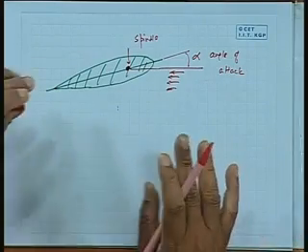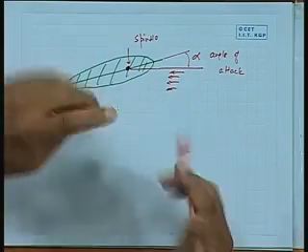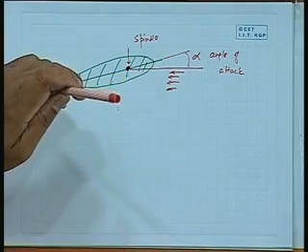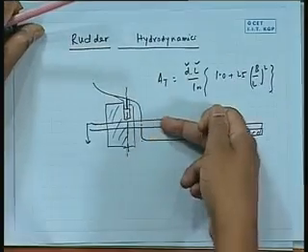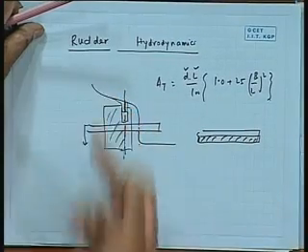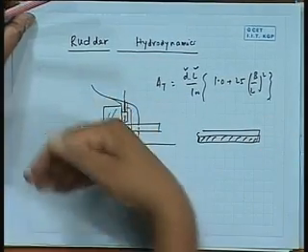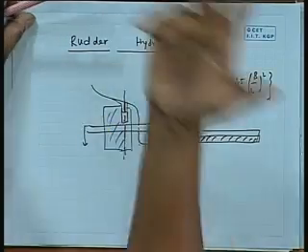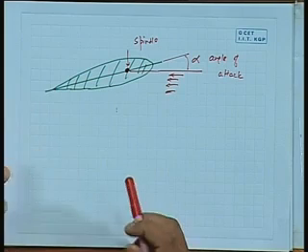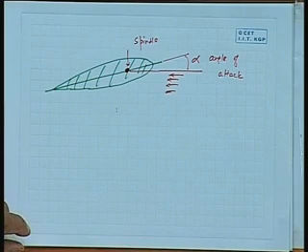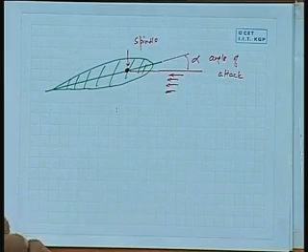Let me again say, if you take a cross section of the rudder, see, first of all, why cross section for hydrodynamics? It is only obvious because you would expect the flow along the rudder to be along this line, not having a vertical motion much. So any cross section you take, you can find out, and you can take each cross section, add them up, you will get the total force more or less. So therefore cross section is a very logical approximation, and I want to tell you what kind of forces will be acting on that.